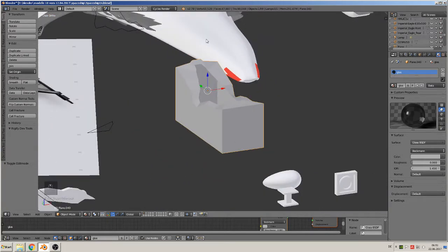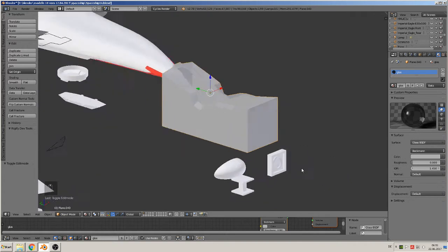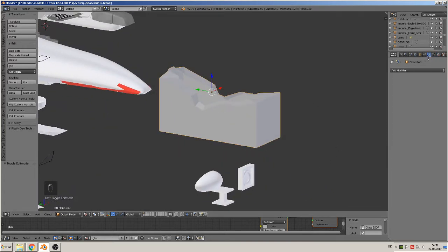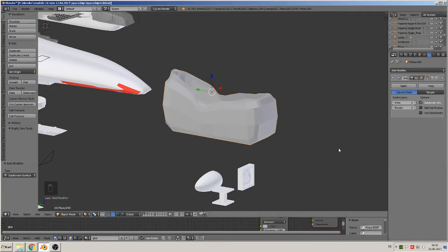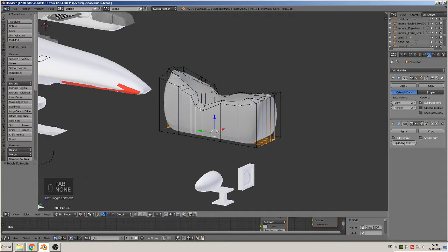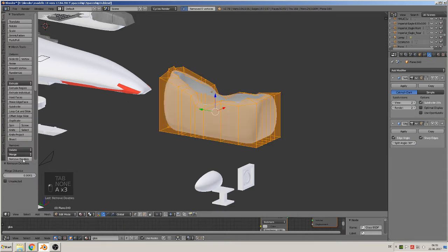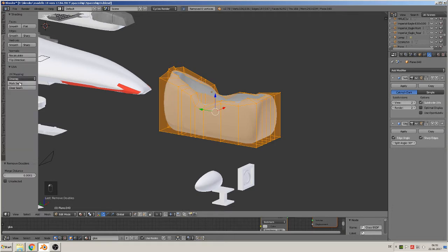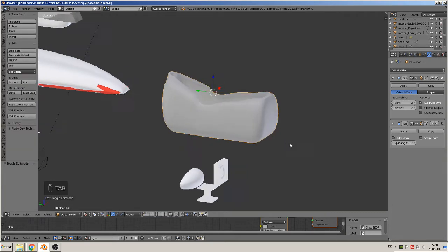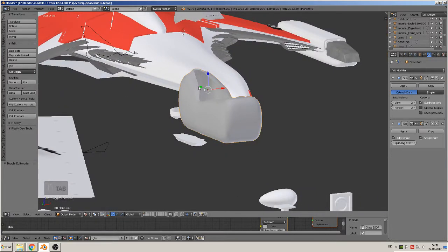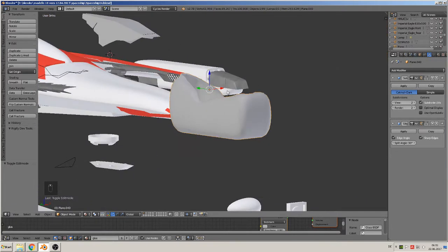So how can we make that as round as that and with this tip here and the background? Yeah, we use for that a modifier, a subdivision surface modifier level 2, and smooth on. And you see that. Then we add an edge split, go in and do remove doubles and a recalculation here. So we have that. That is absolutely fitting with our window, surely, but it isn't really round here.